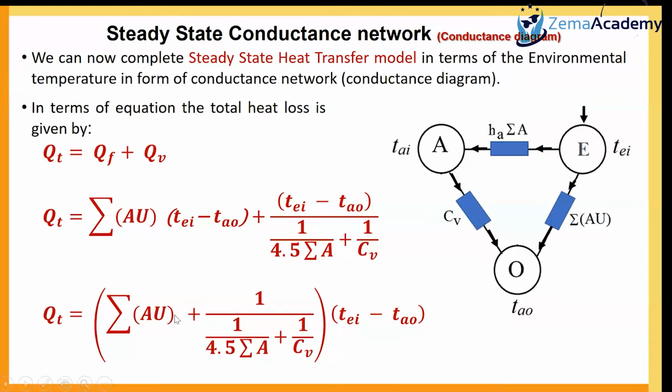Here, the fabric term appears almost as it is, the way it was in the first example. The term involving ventilation has been modified, and now it is incorporating this term, which is any heat transfer that will happen through the convective process.